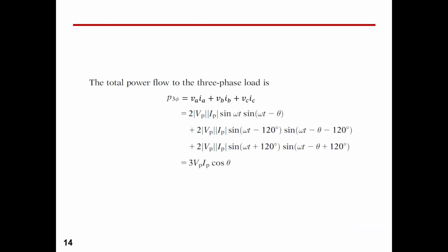What about the power? For balanced three-phase systems, guys, and this is going to be the case all of the time in our electrical machines courses, we have the definition of active power equals 3 V phase I phase cosine theta, where theta is theta V phase minus theta I phase.